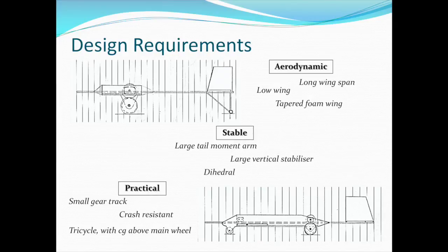Further design considerations include a tapered wing for ease of modeling, long tail distance to improve stability, tricycle gear to make full use of the ramp, and design for crash resistance and repair. The second sketch now evolves to account for the design considerations.